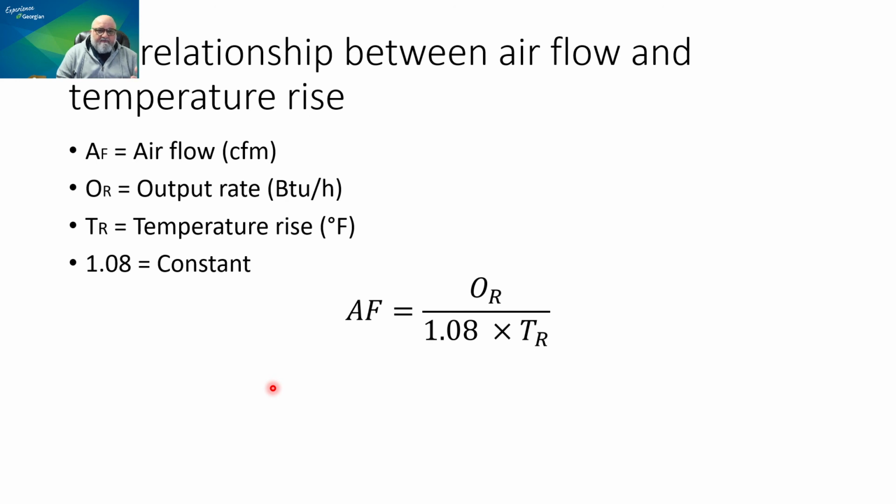This will result in buildup of heat in the furnace, and that will result in tripping the high limit switch. If the high limit switch is automatically reset, it will turn into the furnace running, overheating, stopping. Before it delivers enough heat, it will stop, and then the high limit switch will reset, and the cycle starts all over again. Am I clear?